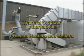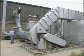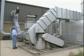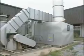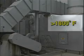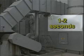An alternative to installing a thermal oxidizer is to incinerate the contaminated gas stream in a process heater or boiler. This avoids the capital cost of new equipment. The contaminated gas stream is typically injected close to the main burners or may be used as part of the combustion air supplied to the burners. Process heaters and boilers are normally designed to operate with combustion chamber temperatures greater than 1,800 degrees Fahrenheit, and with flue gas residence times in excess of 1 to 2 seconds. These conditions are similar to those of conventional thermal oxidizers.